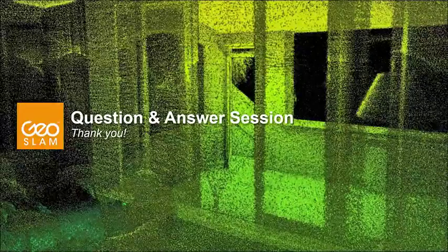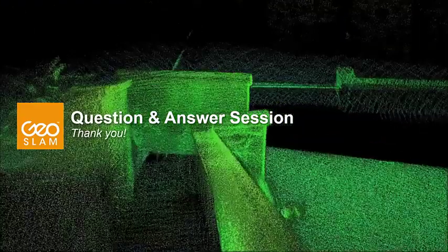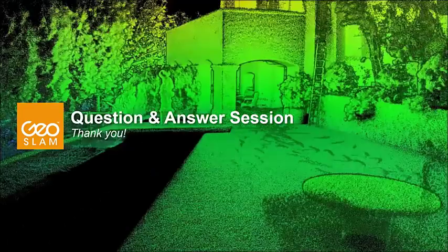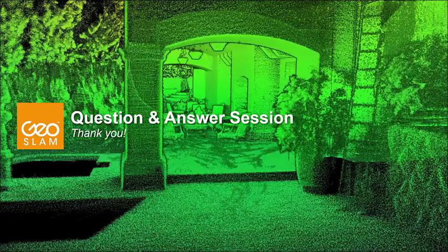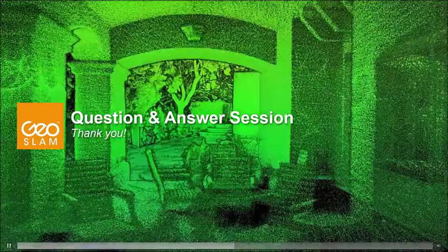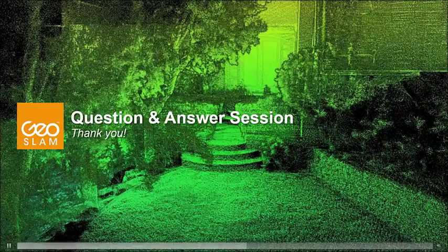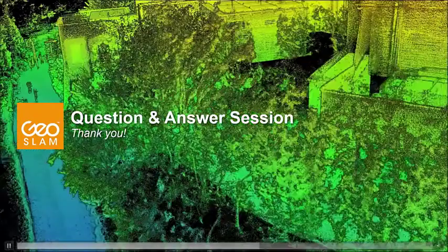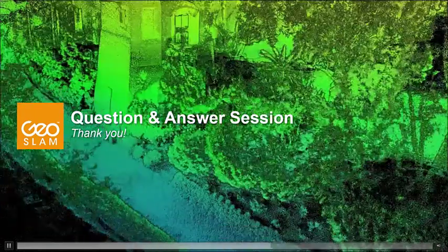So really the trade-off here is a couple things. The trade-off is accuracy and point density. Those static scanners, because they're not moving, are able to capture a lot more dense data in a small space. And we also have a bit more of a noisy solution, so it's going to have a bit more noise in the data compared to a static scanner. So some of those smaller elements, like small pipes or small architectural elements, are going to be kind of hard to pick up.